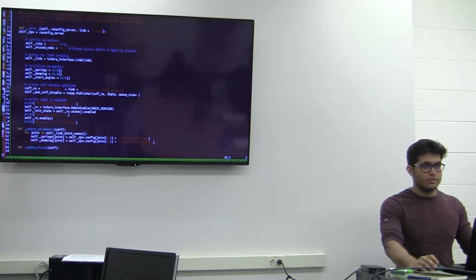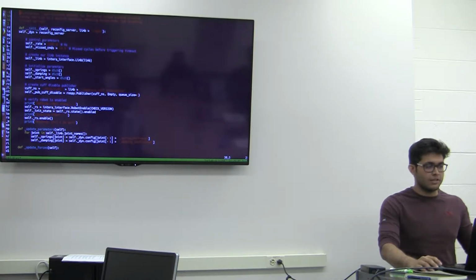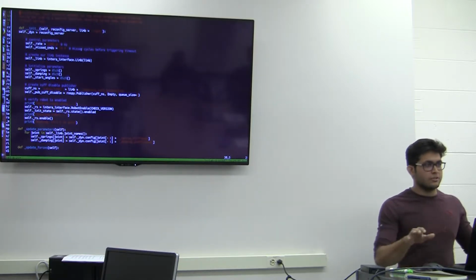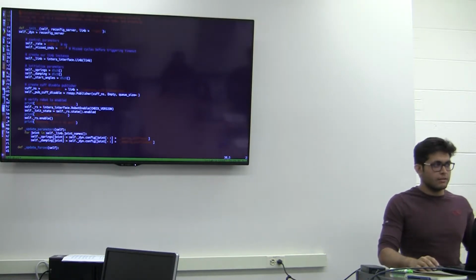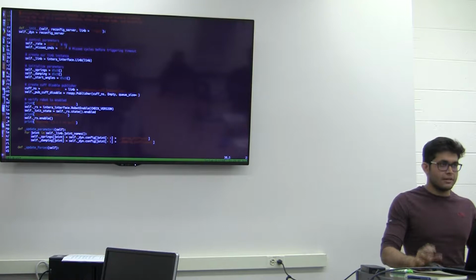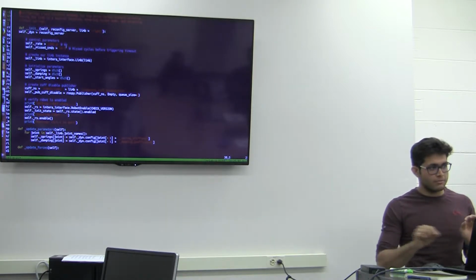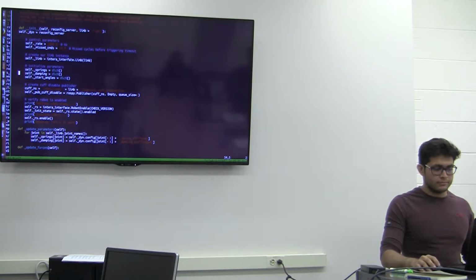Control parameters. You saw it in the Turtlebot tutorial. I'm pretty sure you at least saw the rate part, not the Python file, but you saw the rates, like how it communicates with ROS states and stuff. Miss commands is just like how to trigger the execution, like nope, it's not communicating anymore, and how to stop it. So it just sets it to 20. Like if they miss, ROS time publishes every, like you have the ROS time and you see when the commands are published, right? When you echo the topics, you can see how the topics are published. So if it misses 20 cycles of that, it will stop communication, stop the flow. And spring, start angles, cuff disabling,